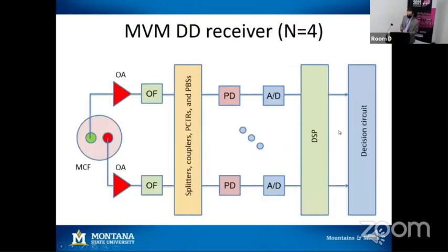Going to the receiver, we first optically preamplify the signal, and then we have a matched optical filter in order to reject as much as possible out of band noise. And now you have to realize that the Stokes receiver actually is an interferometric receiver. So what it does is it takes pairs of components of the electric field and interferes them by making a superposition and taking the square modulus if we assume that the photodiode is an ideal quadratic receiver.